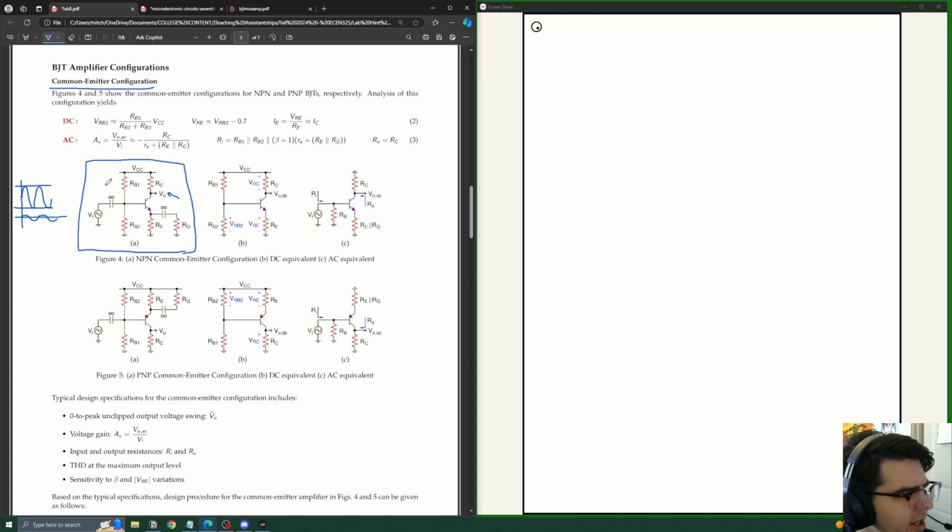Now, I think one other common confusion is, what are these infinite capacitors? Remember, capacitors block DC, because they charge and fill with the DC and then displace it. So the whole deal with this infinite capacitor is that when we consider just the DC, the capacitors are open, leaving us the DC component right here. When we're looking at AC, the capacitors end up being shorts because their impedance is 0. So that just gives us the AC component right here. It's purely a modeling choice to show how we decouple the two effects in our analysis. So you'll just pick a large capacitor in your simulations, like a 1 farad capacitor, and just leave it like that.